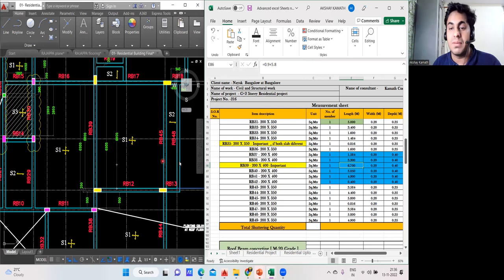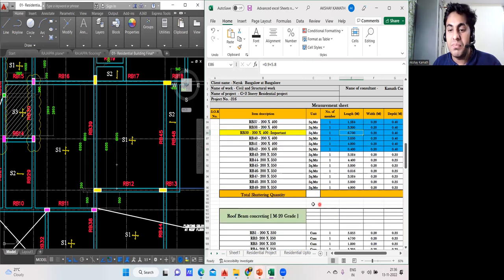So quickly, let me do that. I'll quickly do it somewhere here. So tell me, open the bracket. Exactly 6.7. You multiply this by the breadth. So breadth is 0.2. Done. Close the bracket. Again, plus open the bracket. So this time you take the complete length. What is the complete length? It is 6.7. Agree with me, no? This complete length where my shuttering will happen is 6.7 only.